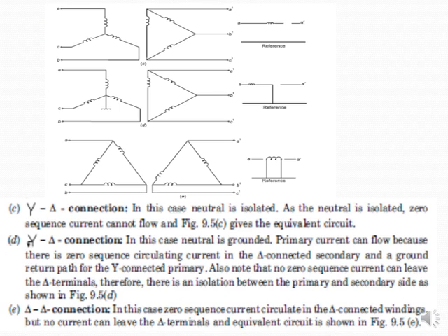Then where you've got your unearthed Y connection to your delta connection, you can see that I draw in up until that point and then it's open where it goes to my delta connection. Then where I have an earthed Y connection and a delta connection, you can see that I come in from my star and go down to my reference voltage, and for my delta it is an open circuit. Then where I've got a delta to delta, you can see I've open circuited on both sides, and then I just show the transformer going down to earth on either side.